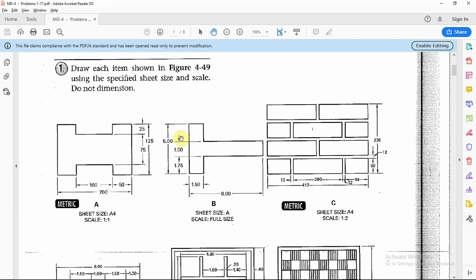There is a reason why, because this dimension is not shown, and that is because the standard for mechanical drafting is not to give redundant dimensions. We get into precision and high accuracy later. We'll discuss why. But again, they don't. The standard is not to duplicate dimensions and not to provide redundant dimensions. So that's one of the reasons why it always seems to be lacking.